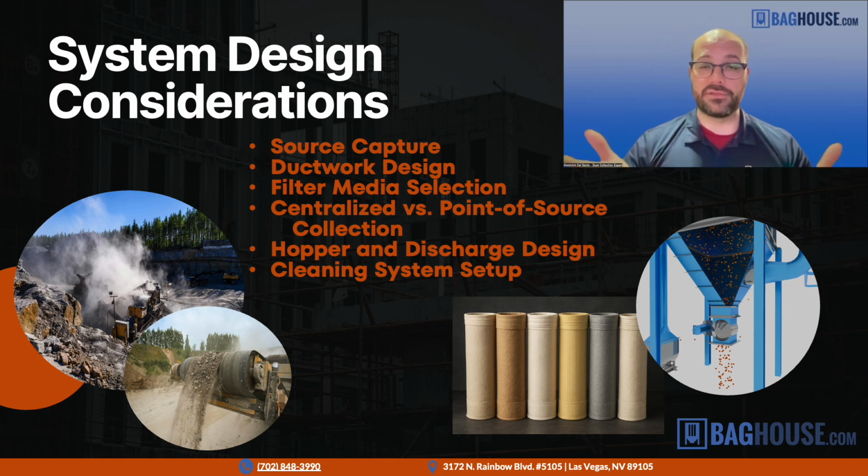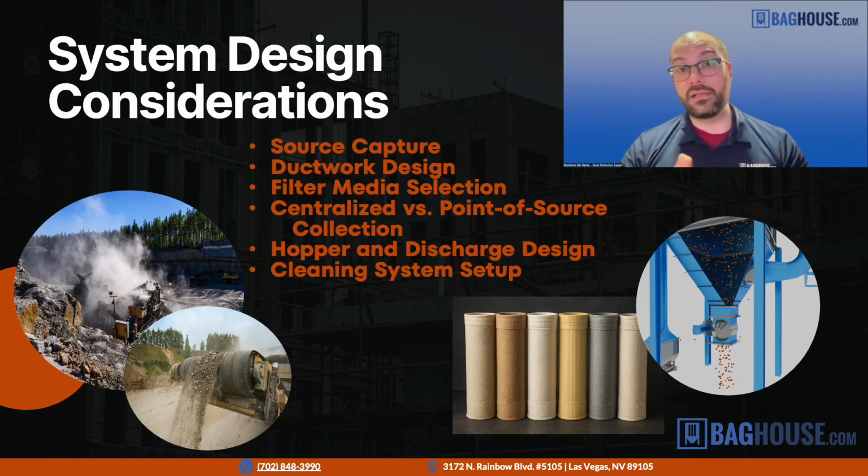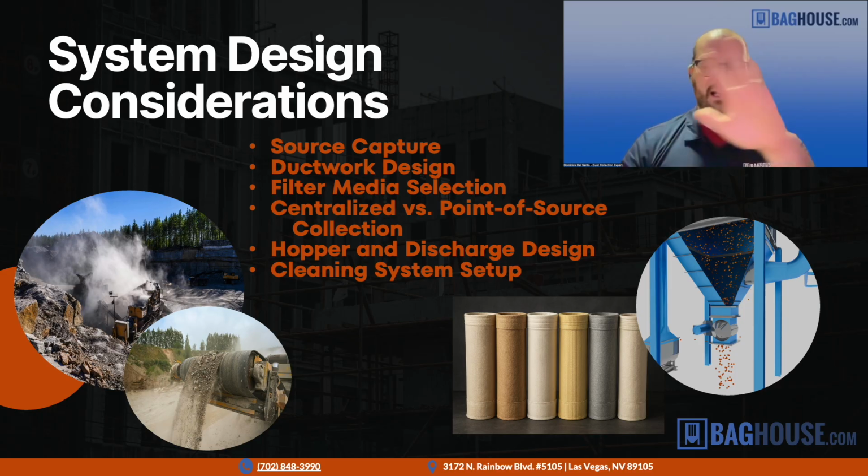Make sure that we have a sufficient design that allows the dust to be removed and not get stuck in there. So that may involve using things like vibrators or aeration devices that keep the material flowing and emptying out of the baghouse. But also, whatever comes under the dust collector, so the rotary airlock, and then whatever's underneath after the discharge, we need to consider that as part of the entire system.